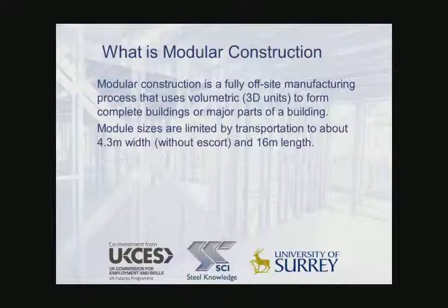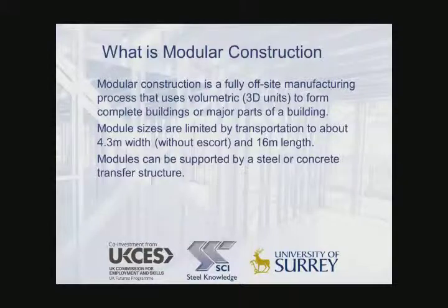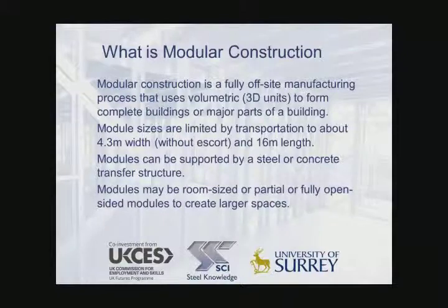Module sizes are generally limited by transportation to about 4.3 meters wide without an escort and up to 16 meters in length. Modules can often be supported by a separate steel or concrete transfer structure, particularly over open areas. Modules may either be room-sized or partially or fully open-sided to create larger spaces. And the term pod is generally used for non-structural modules placed on a floor.